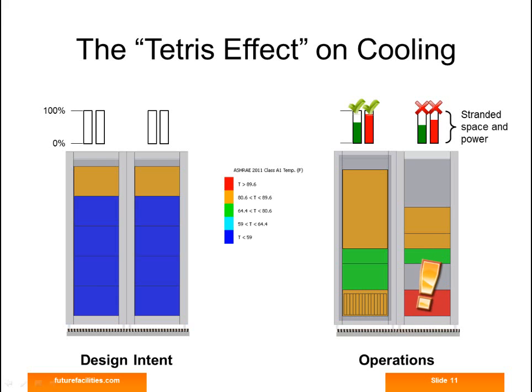Cooling, on the other hand, is indirectly coupled to the IT equipment by airflow. Airflow can fragment anywhere, and often everywhere, in between the cooling units and the IT equipment. DCIM tools completely overlook this characteristic of the cooling distribution. But this is not the only problem. Airflow is invisible; it cannot be measured with sensors. DCIM tools with temperature monitoring can warn the operator that temperatures are rising, but they cannot show the cause of hotspots, which are airflow related. They cannot be used to fix the problem.